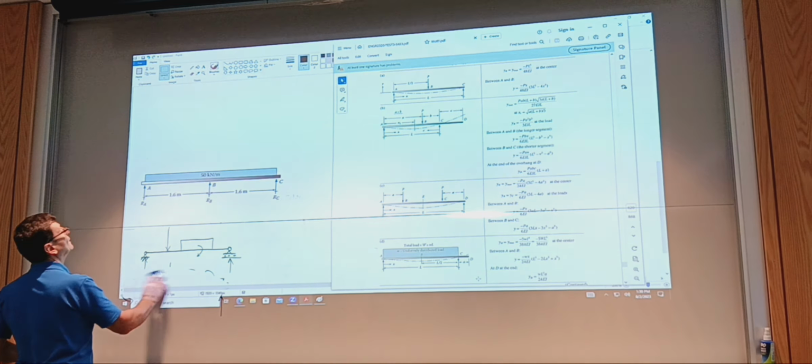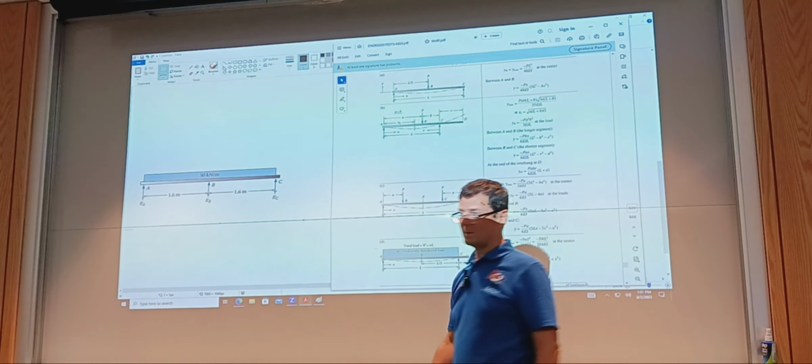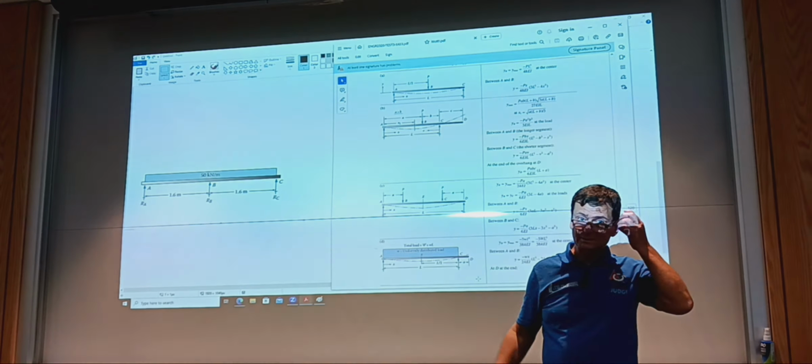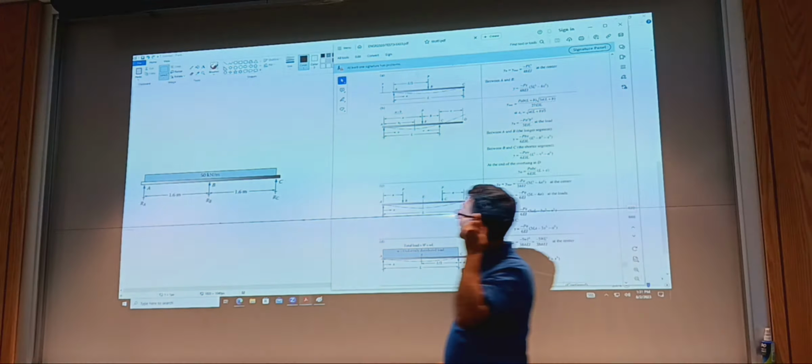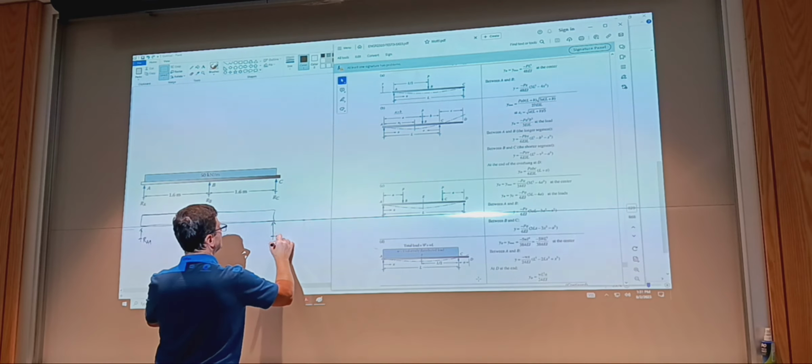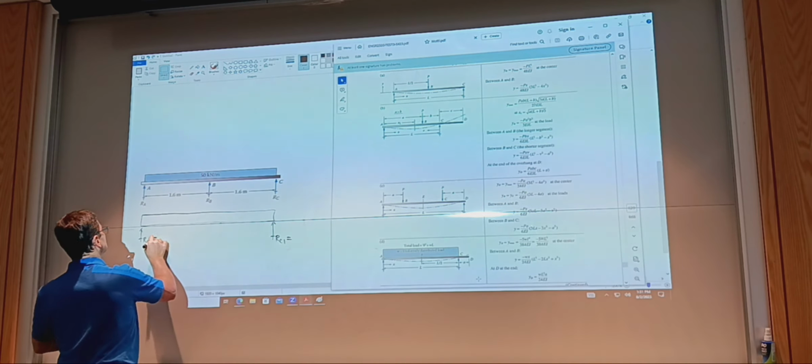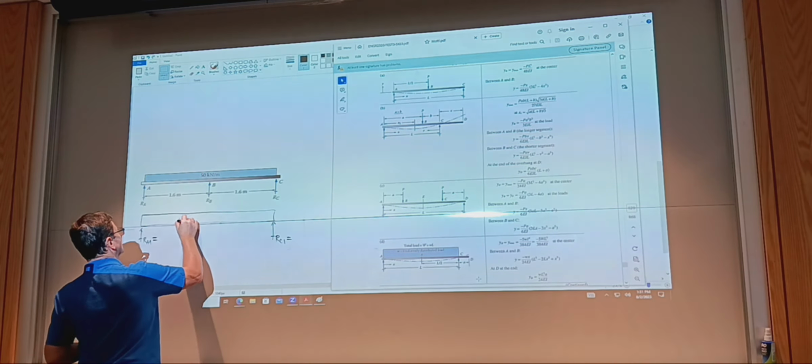But we can use the formula method to figure out this kind of problem. So we can assume this to be an overlap of a statically determinate beam that is loaded with W. So the reactions of the supports for this instance are RA1 and RC1, equal to W, which is 50 kilonewtons, and L, all right?